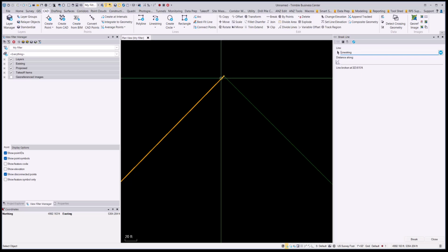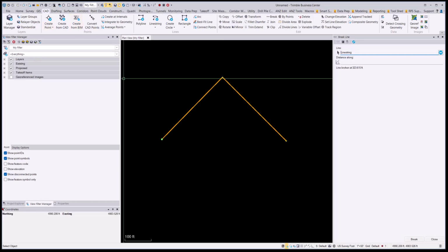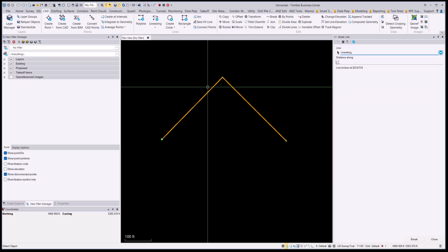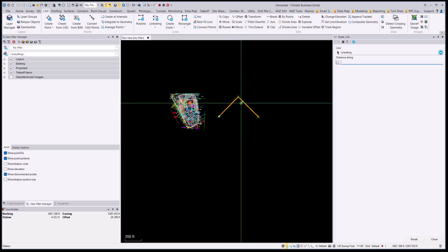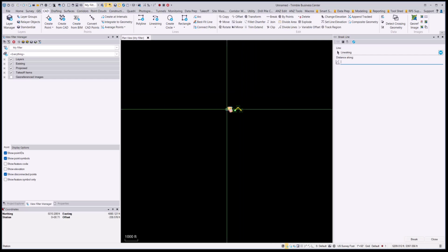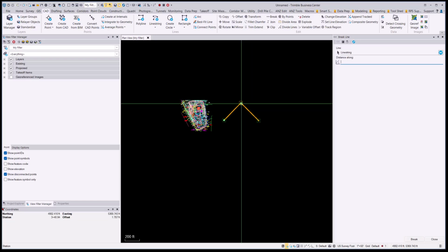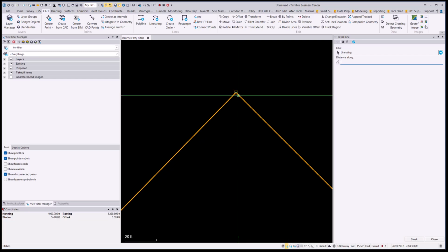Okay, so if I'm trying to break things and trying to find corners, I want to be specific on where I want to break it, and I want to make sure I'm paying attention to where that snap's going to snap to. Okay, and again, zoom is free. So if I'm trying to break something and I'm zoomed way out, I don't know where I am picking. Okay, so this one's quite obvious because it's on a large scale, but if I'm working over here in our data, zoom in and see where you're picking, so you can get close to that corner and then break it.